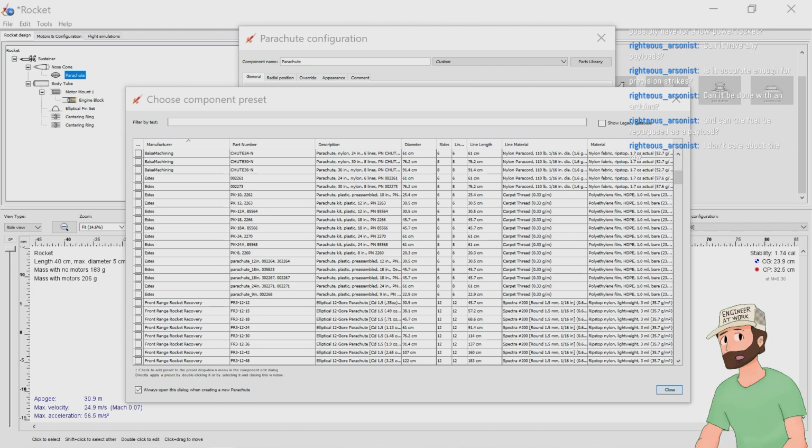Parachute design. Use of a spill hole. Okay, so parachute size. As a general rule of thumb, the design descent velocity of your rocket's parachute is 3 to 4 meters per second. You can determine the area of your parachute from the following equation.